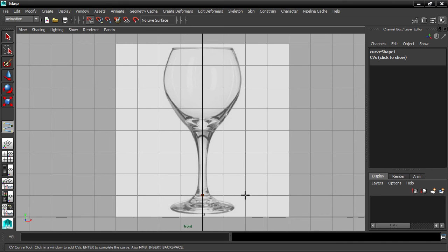And likewise out here, I'll go out here and still holding down X, I'll click once and then give a pause and then click a second time. And that way I create a perfectly straight line there. That's how we do it with NURBS. If you want to have a perfectly straight line, then you need to double up those control points. You need to have at least 2 control points on top of each other. All right, now I can relax a little bit. I can let up on that X key and I'm no longer snapping.